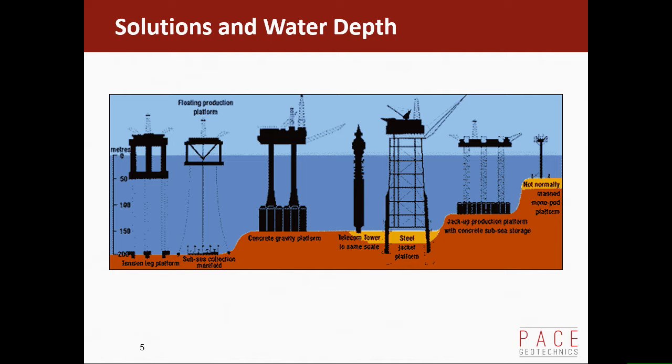Jackups: that's a version of a jackup which is actually designed with oil storage at the bottom. A more common jackup would be a drilling jackup, which I'm not going to talk about here. But they land them on the seabed and push them in a little bit with preload, and that gives you horizontal capacity. It's a form of gravity base in effect.